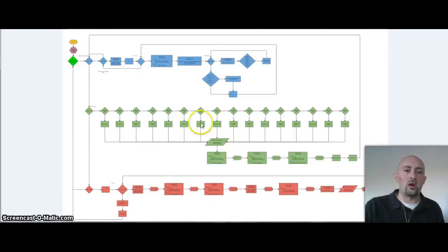And so then we can come over here and we can actually look at my flowchart. So here I have an input state for looking for button pushes on the actual keypad. Here we have the storage state, so once a button press has been detected, we go into the storage state. And then down here we have an output state, so once 2 buttons on the same row have been pushed on the keypad, we will then go into an output sequence displaying all of the buttons pushed, in the order that they were pushed. And so that's the basic flowchart for the program.